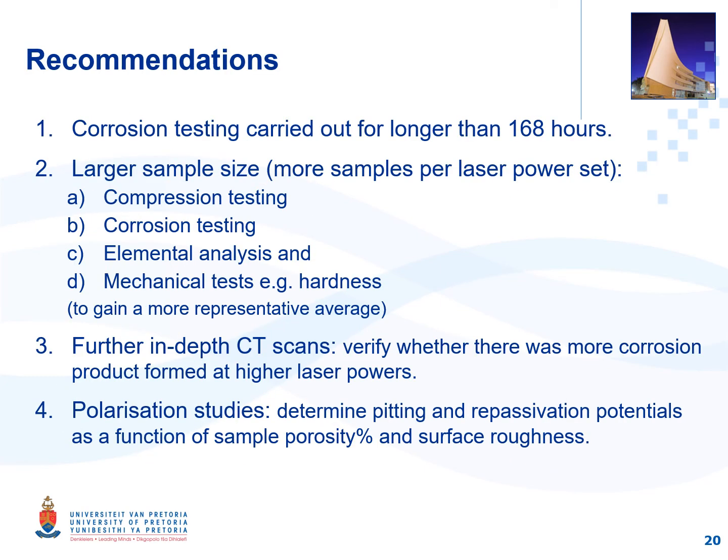In order to gain an in-depth understanding of the effect defects such as porosity has on the corrosion of these alloys, it is recommended that corrosion testing is carried out for longer than 7 days. A larger sample size is used to allow more samples per laser power set for different tests.